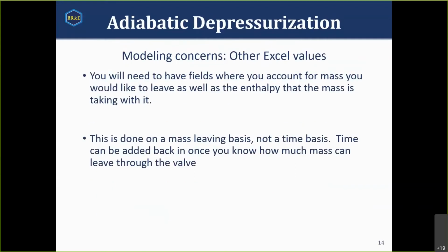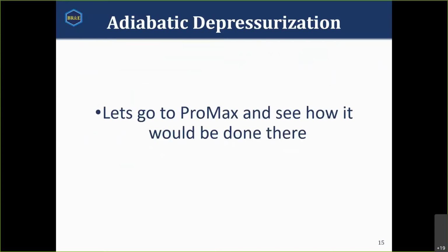I do want to mention one more time, when we are doing this together, we will be doing this on a mass leaving basis. I'll be saying at each increment, we will be losing 10 pounds. This does not mean that it's going to be equal time. The time for 10 pounds to remove is going to change, of course. As the pressure of my vessel decreases, we will be venting less and less. We're ignoring the time factor for the purpose of this exercise, for the purpose of understanding concepts and simplicity. So now let's get to ProMax and do this.